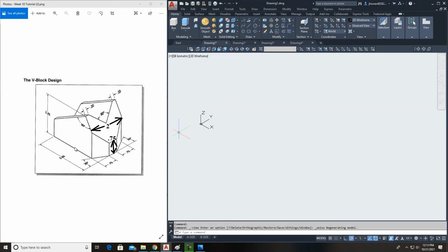I want to do a rectangle 3 by 2. I had to draw that in because it's missing some information. But anyhow, this is in your book. You can go to your book, and this is the tutorial that's in there. It's in chapter 4. But I want to go in here and start drawing this. Rectangle 0, 0, and this thing is 3 for X, 2 for Y. So I've got that in there.